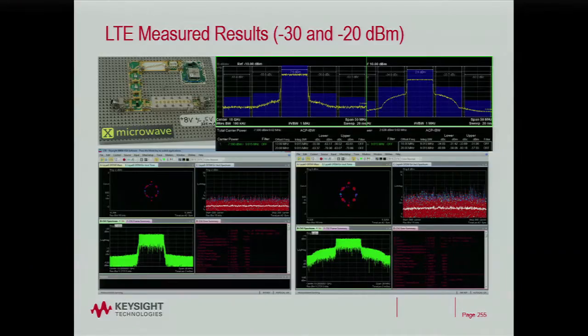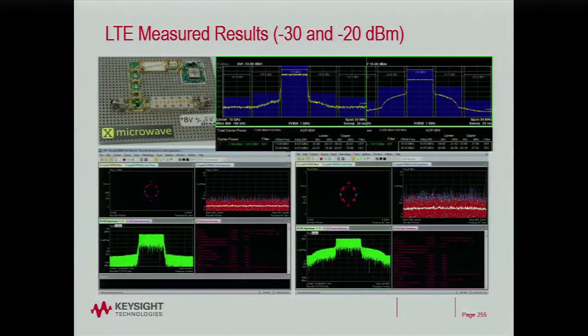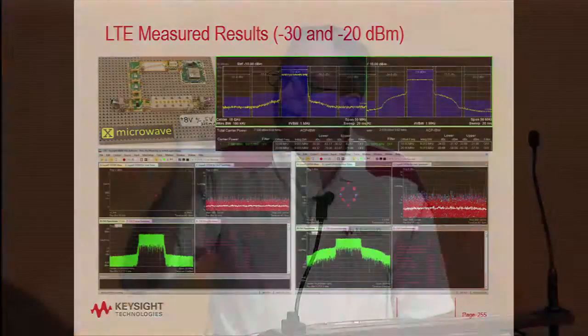And so they have a system where you can quickly design this middle piece of the transmitter, which was IF in, and there's a mixer, and then an up converter. At the top, on the right, you see the 5 gigahertz LO, and then it's multiplied and amplified, and then it comes down into the mixer, which is the little black dot over at the left. And then we have an 18 gigahertz filter at the output. So this system, X Microwave, helped me get part of this design done very quickly.